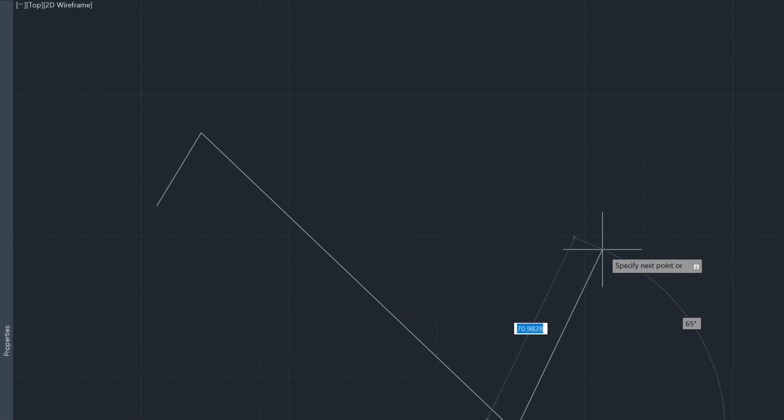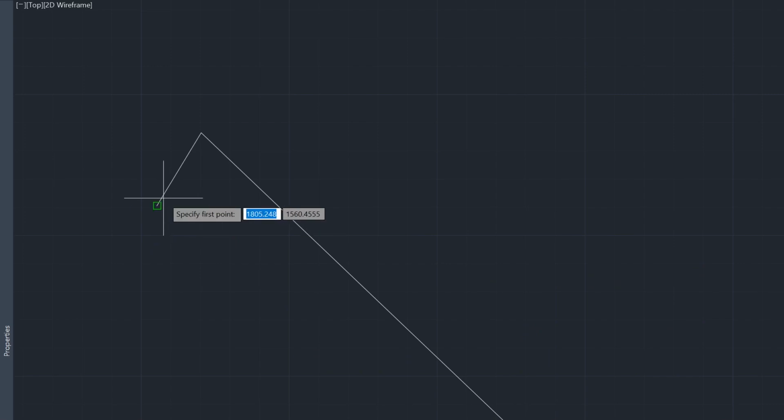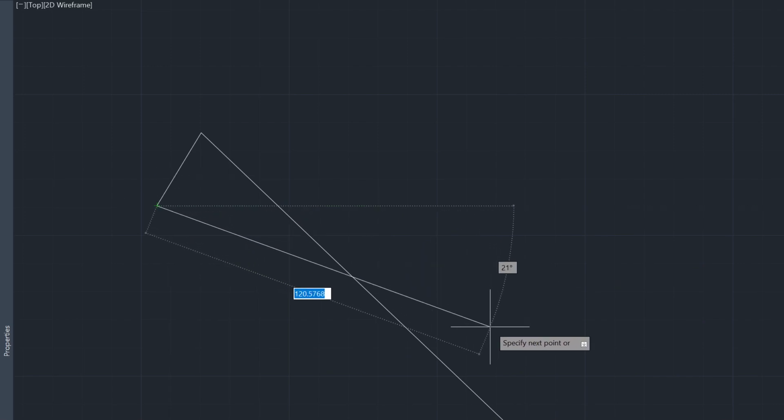And then off the other line, we're going to draw this at 27 degrees. Remember that you can just draw the lines parallel, right? So you don't need to get the protractor out. There's an easy way to draw parallel lines. I should have shown you this in class using just a set of set squares. Okay, so again, we'll just go with a big line. We'll go with 120, looks like it's big enough. And what was the angle? 27 degrees? Okay, so 360 minus 27 is going to be 333. You happy with that? Yeah. Okay, and then we can just trim those.